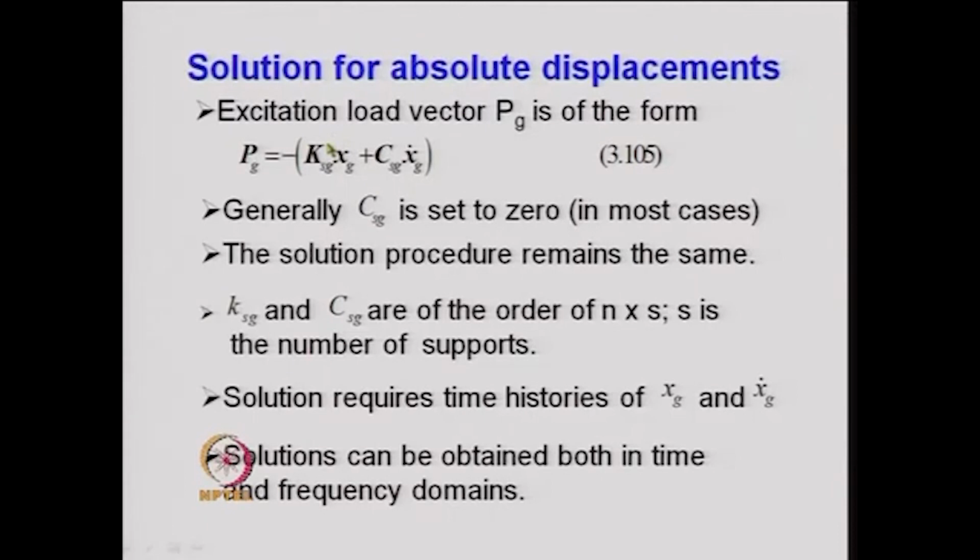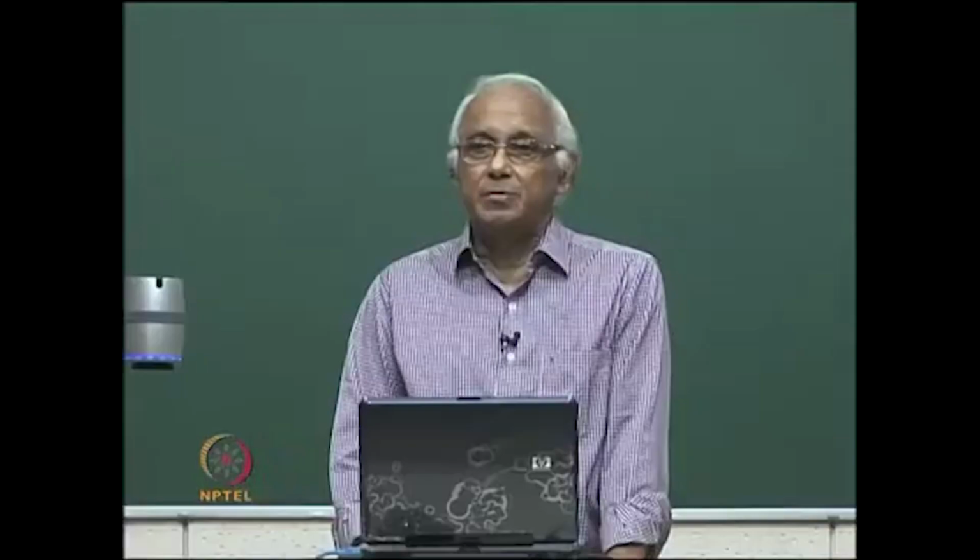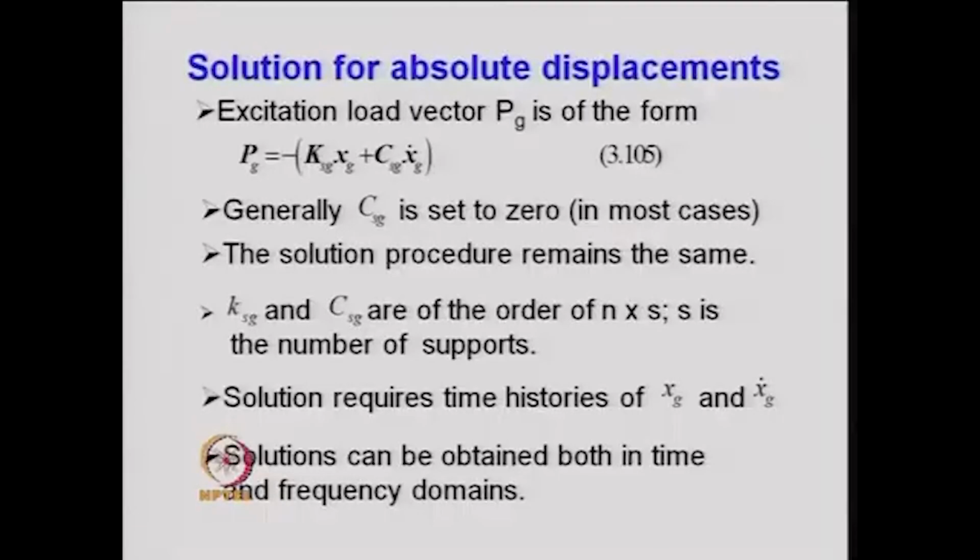So, by knowing not the ground acceleration, but the ground displacement, one can obtain the value of the Pg vector over here. And once we know the Pg vector, then we can solve the problem either as a second order differential equation or in the state space, and we can use whatever method we want, that is, we can solve it in time domain or in the frequency domain.